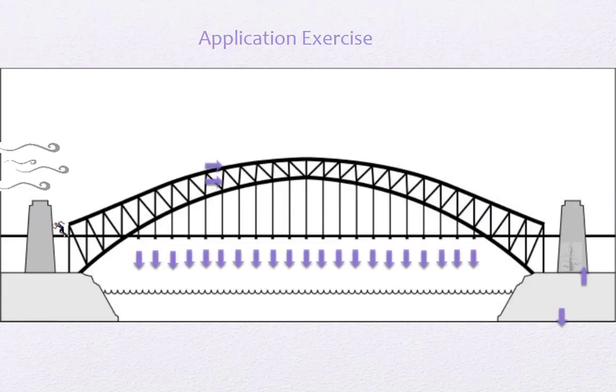the settlement loads on the material that it's resting on, the thermal loading for the expansion and contraction of the elements, seismic loading for withstanding earthquakes, and the shrinkage of concrete for when I use concrete on my supports.